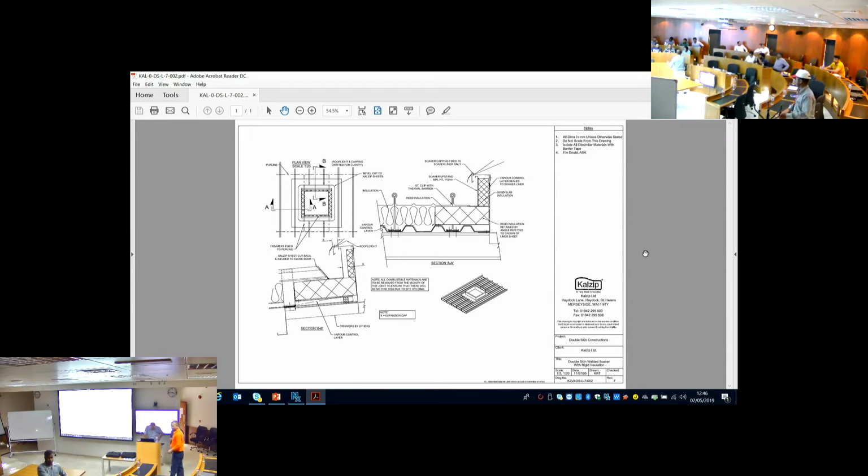This is part of the problem that I've seen here too many times. It's exactly that. They bind the flashings so that when it moves, there's no movement in the flashing. That's right. The flashing itself doesn't move, and what happens is it kicks it that way.